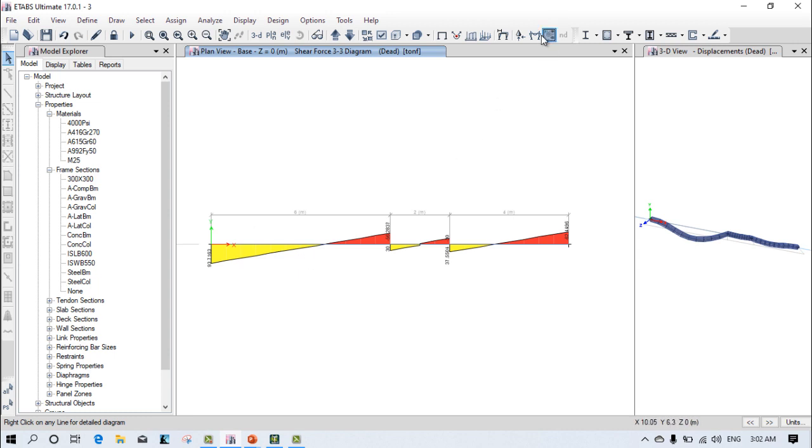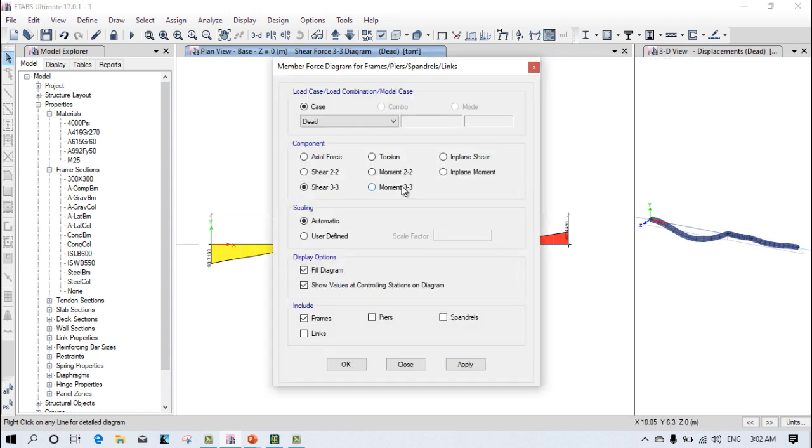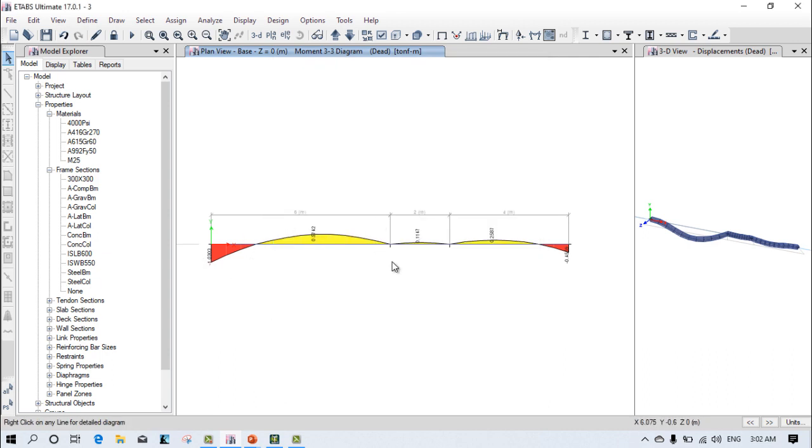But in terms of the shear movement, the deflections will not be that much, because this value is reflected with respect to the other values. In every software, the deflection you see is with respect to the present values. So accordingly 0.11 versus 0.5 is a very huge value, and that's why you see the deflection like this. Don't go for the diagrammatical changes, go for the values.